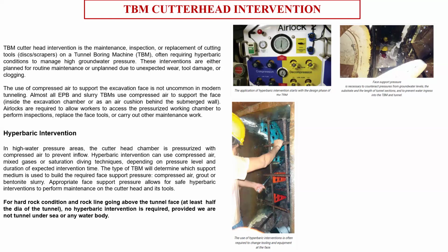Basically, what happens is, once the segment is deviated out of the curve, out of the alignment, we cannot rectify the segment or redo the alignment. So what we do is try to adjust. If the deviated part is very close to the station, we try to adjust with the station alignment. If it is mid of the station and the tunnel, we try to adjust in the track part because the track also has its own tolerance. So we try to see if it can be adjusted in the BLT track or not. It's a very interesting case because there are lots of things I have done for this project, on how it was finally adjusted after the legal survey data.